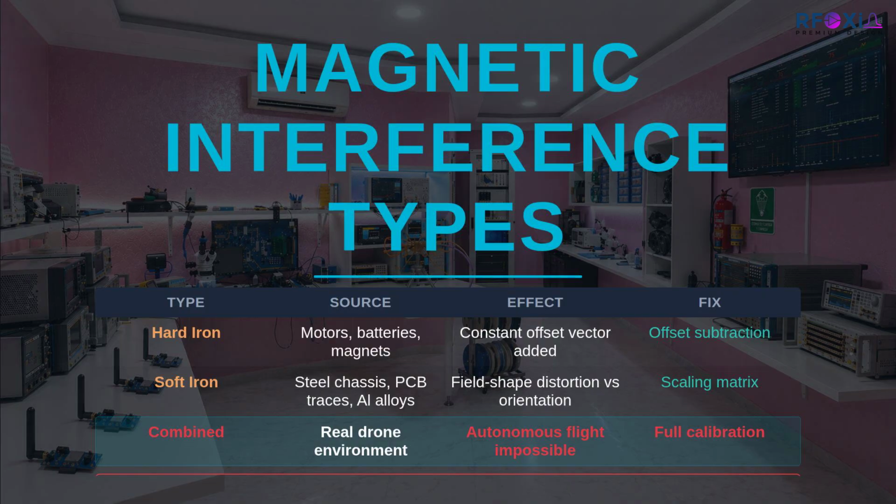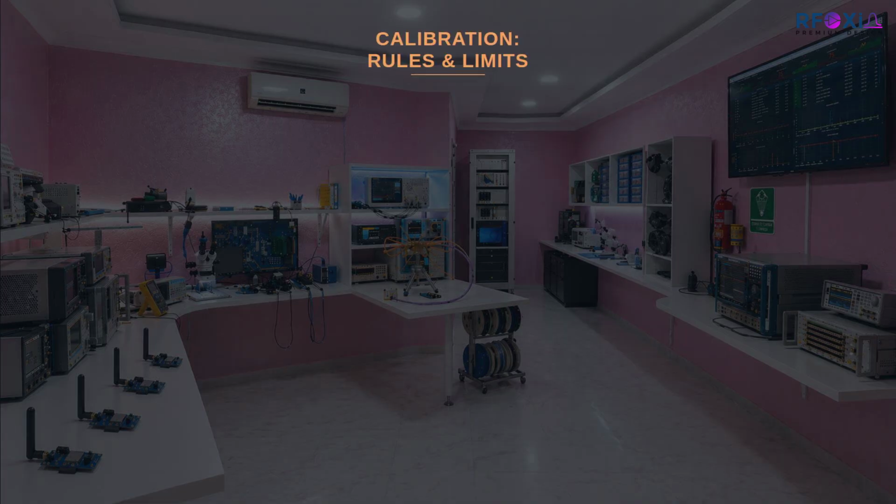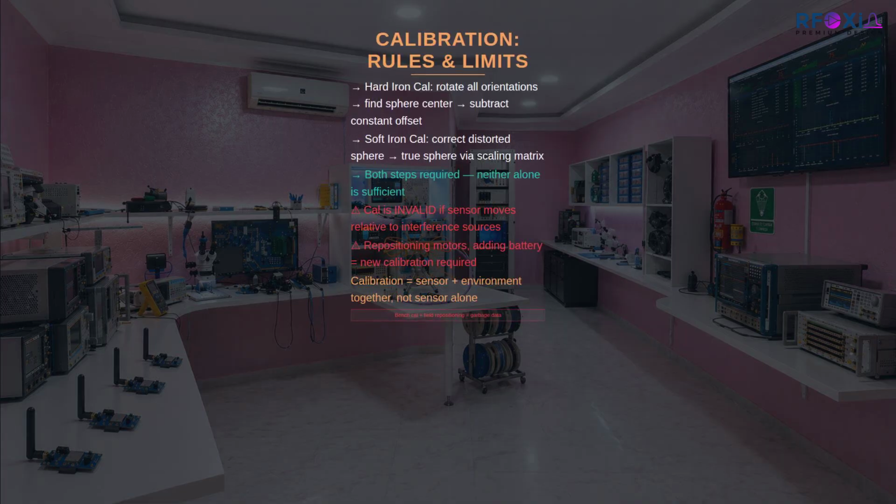This is why placing the accelerometer, gyroscope, and magnetometer on a single integrated module matters more than it sounds. When the three sensors share a rigid substrate, their relative geometry is fixed by the PCB. The calibration you perform for the magnetometer remains valid as long as the module position is fixed. You are not managing 3 separate mounting points, 3 separate coordinate frames, or 3 separate thermal expansion coefficients. The alignment between gyroscope axis and magnetometer axis is defined in copper, not in software assumptions.